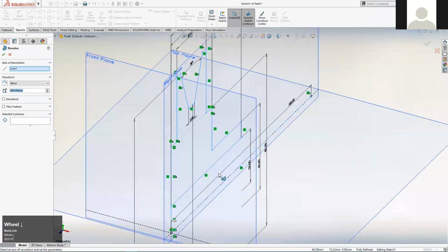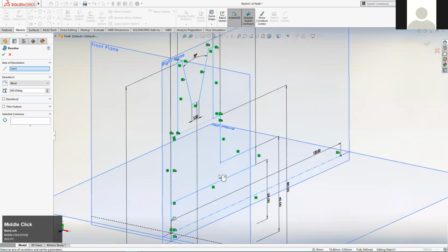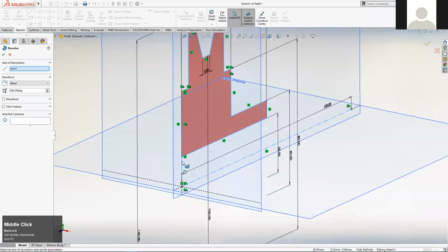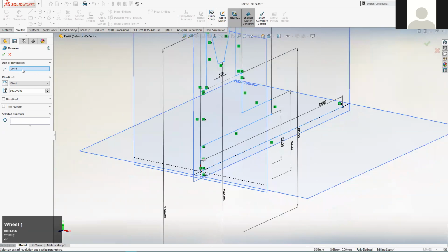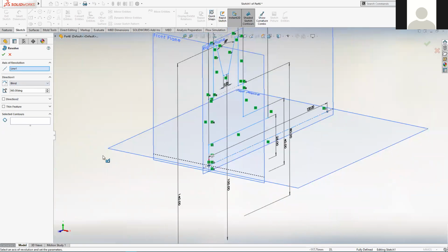Ooh, I've done something here, and I did this before. While I was talking, I forgot to delete that initial line. If you remember, I put that initial line in just to give me the rough position of my first horizontal line in my sketch. So that line there is breaking my sketch. The system's saying, you've put a line in there that isn't a part of the closed boundary. So it's unwilling to create an extrusion for me.